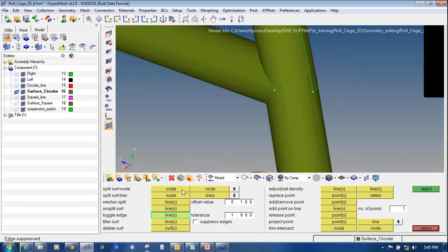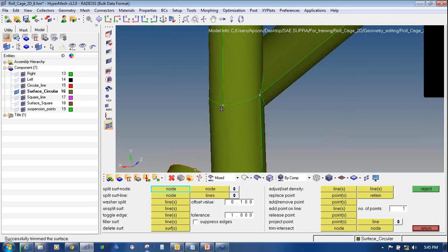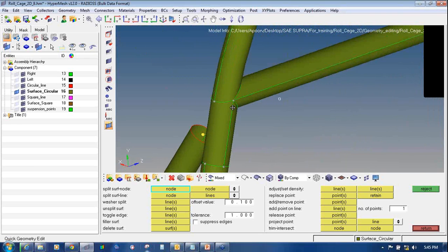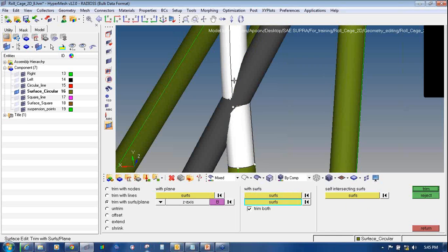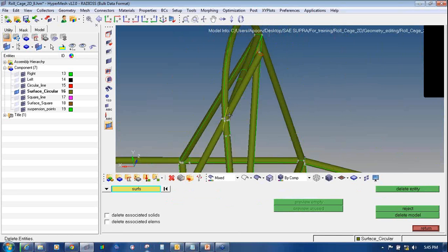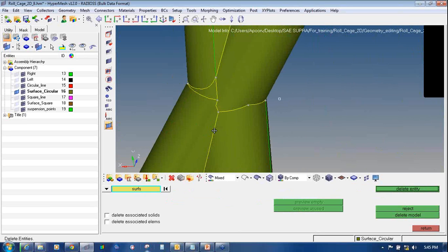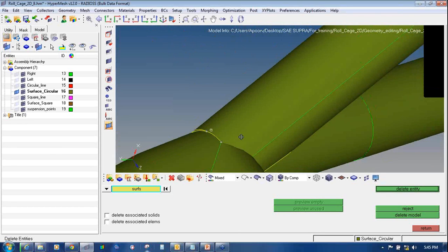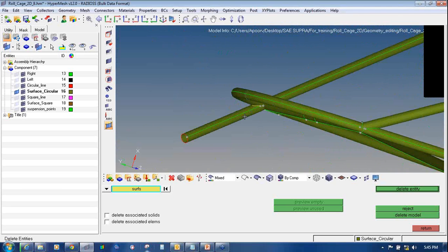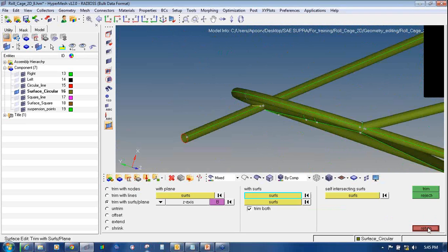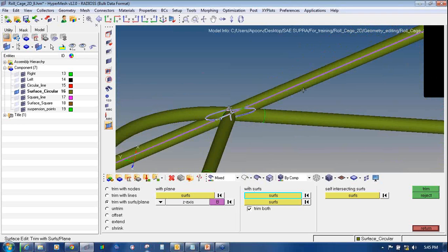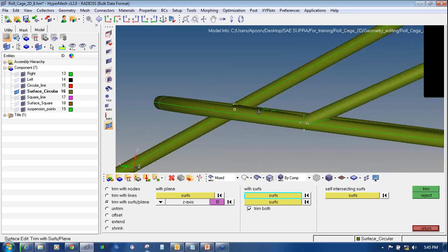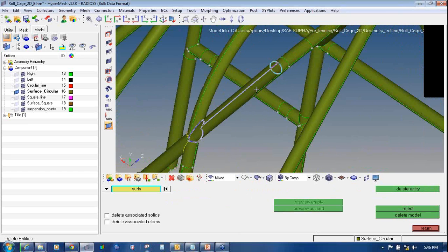Also you can toggle these from this point to this point, you can create a new line. Then Shift F9 again, extend this, pick this surface to be trimmed from this to this. Delete the extended one. If it's not selecting, that means there is something which is not split. So Shift F2 and say clear all first, and just check where it is not split. You can see this pipe is not split, so I will select this pipe too. Then go to delete panel and select this.